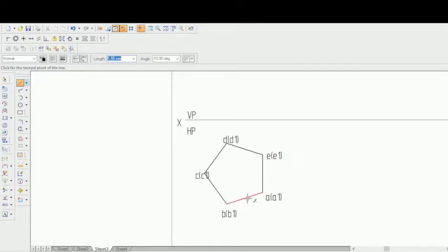From there, join that line to the opposite corner. Do it for 2 edges. You can see from here, let me draw it to this corner. That means you get the center. So this is the center actually. From here, let's draw a projection line from the center up to this reference line. So now let's draw projection lines up to this reference line. Let's do that.